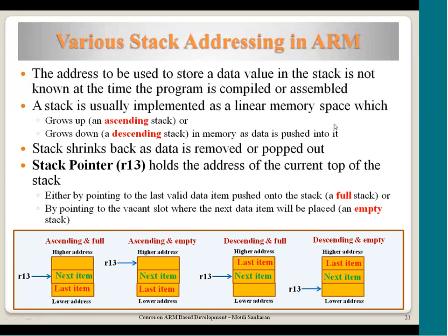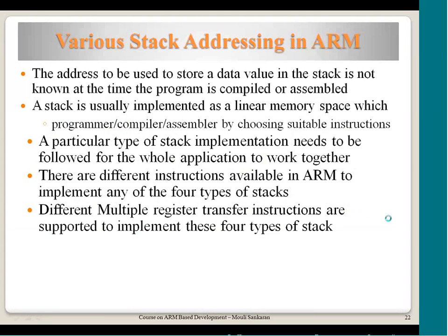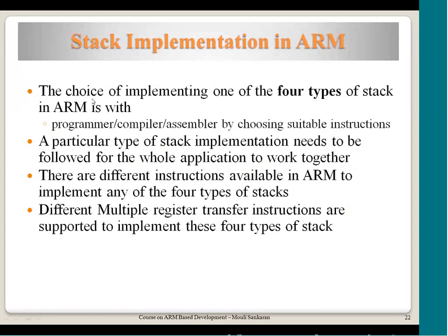Now you may wonder, when the processor is coming up at the reset location, what stack does it follow? There are some push and pop instructions specific to the stack, and they assume descending and full as a default, and then it will be used in any way. And ARM has given different instructions for all these four types of stack. Now let us see who decides which type of stack to be used. In ARM, it is decided by the programmer or assembler by choosing a suitable instruction.